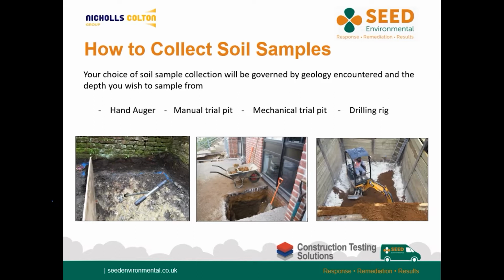However, you must consider the site access and the size and positioning of the spoil heap generated during mechanical trial pitting. For health and safety reasons, where possible, soil samples should be collected from the excavator bucket or from the stockpile to negate the requirement to enter the trial pit or excavation.